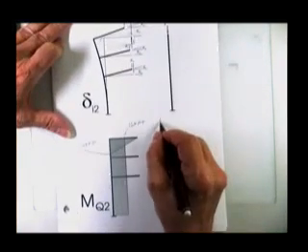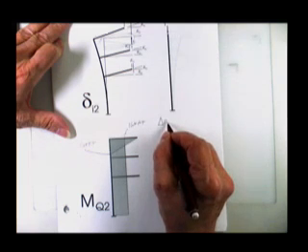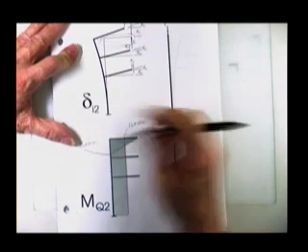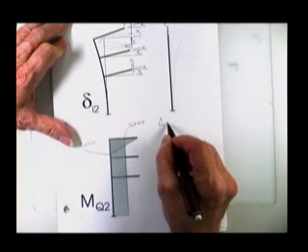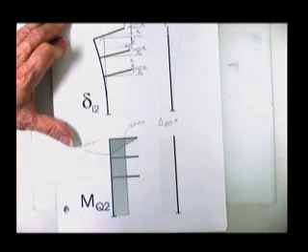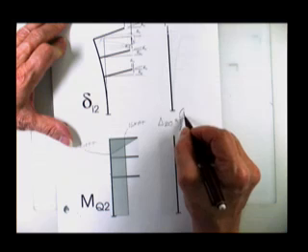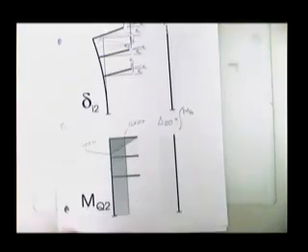If you would like to find the deflection on the real structure, what did I call that thing? Delta is due to the real loads on the primary structure. In the number 2 direction, due to the real loads, you would find it by integrating the real moment diagram, M sub P, 0, is that what we call that guy?